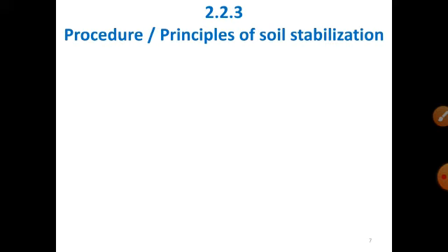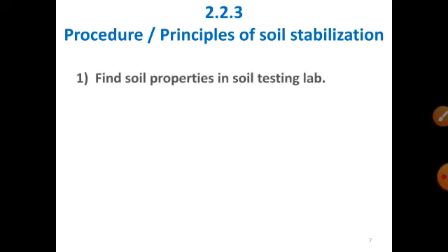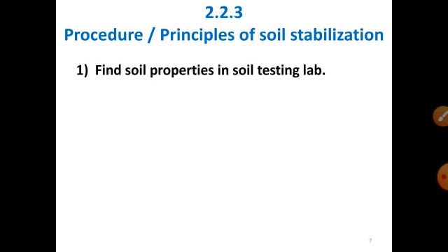Third subtopic, procedure and principles of soil stabilization. First principle or first step is to find soil properties in soil testing laboratory, like plasticity index, plastic limit, elastic limit, etc.